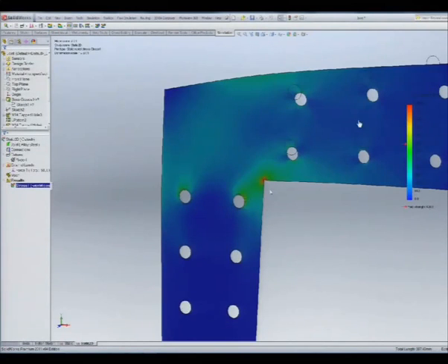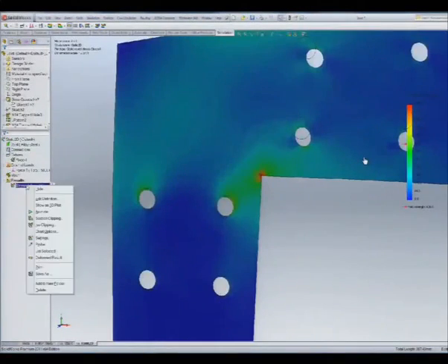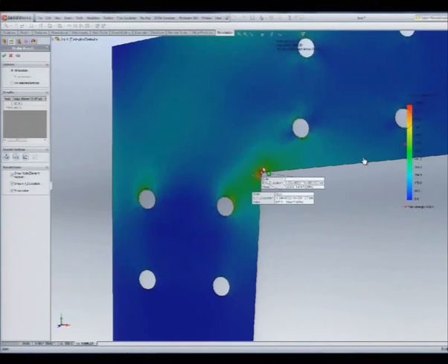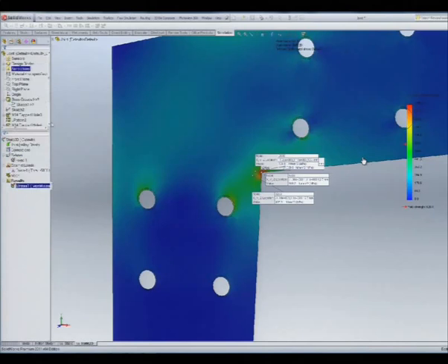In this example, this red arrow shows that the stresses around the corner are higher than the yield stress. So this plate is not good. We have to optimize this stress. So what do you think? What can I do? Another radius, right?